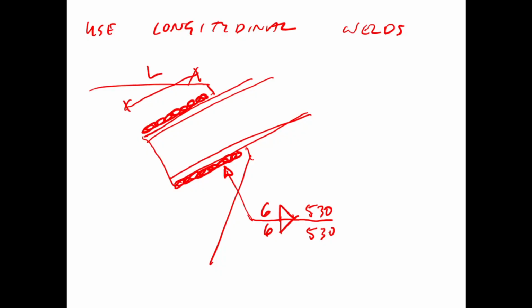So 6 was just like, I can't do more than 6 in the field. Okay, 6 millimeters is the size. It's always more efficient in terms of the weld material to use a smaller, longer weld than a bigger, shorter weld. If you did 12 millimeters, you double your strength, but the volume of weld and therefore the labor you need goes up with that squared. So you need 4 times more weld and 4 times more labor to provide the same strength of weld that's half as long. So in terms of labor efficiency and material efficiency, longer, shorter is better. And the biggest one we can make is 6 anyway in a single pass, and so that's why we chose that.